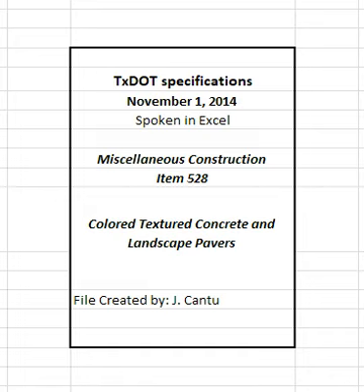Apply dry shake color hardener, if used, evenly to the plastic surface, following the manufacturer's directions. Use at least 65 pounds per 12 square yards. Apply in 2 separate applications and float after each application. Trowel only after the final floating.